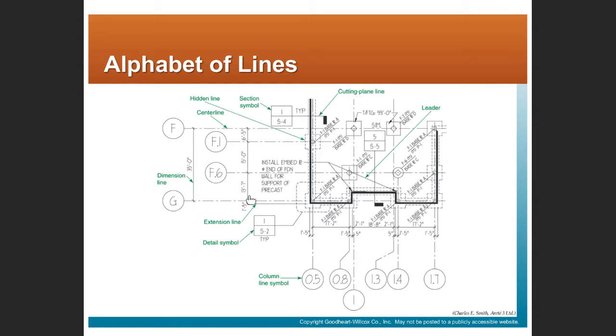Right, and here's another center line of these intermediate footings. So there's what, 13 foot 7 between the center line of this footing and the center line of this set of footings. I'd have to see the whole thing to figure out why there are so many different structural elements here.